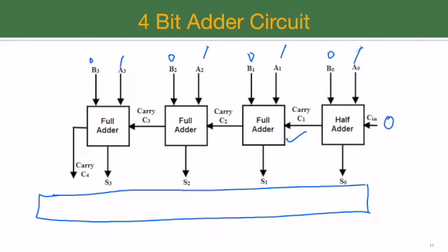Okay, notice, so here the full circuit is, for the time being, ignore the detail of half adder and assume that a full adder exists over here. There's a reason why it is being called half adder, because half adder does not have a carry with it. So this portion can be omitted, but you can replace it with full adder and add a constant 0 bit over here. So notice that the carry produced from the first bit operation is being fed as C in for the second bit operation.